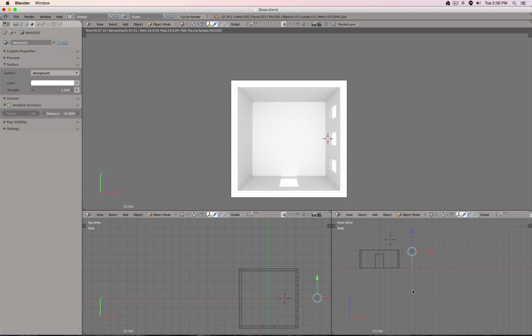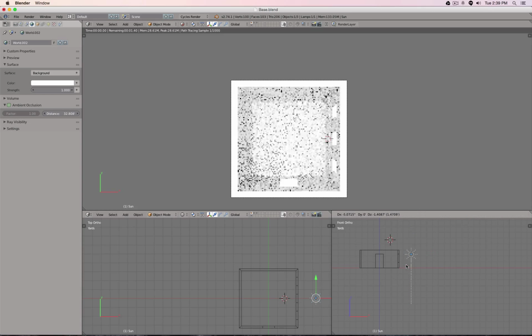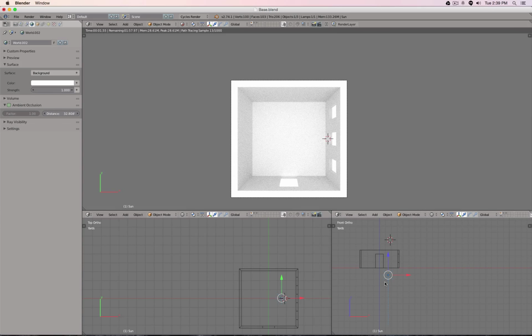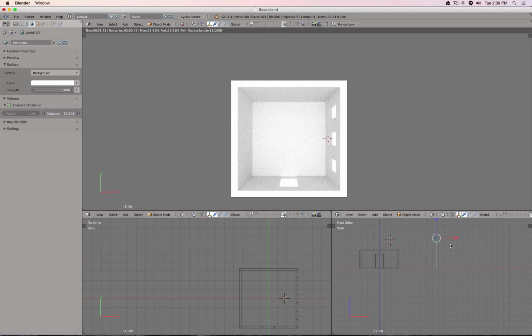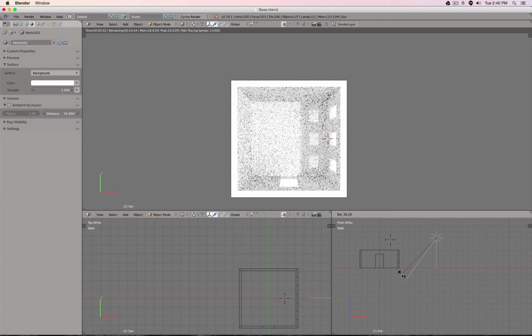That actually decides from what direction the light is being shot into or flooded into the scene. So currently the light comes from the top down. You can even put the sunlight below my house. It doesn't really matter. The sunlight is basically simulating, well, our sun. So it's directional light. That means all light rays are parallel to each other. That means shadows don't really foreshorten perspectively. But I can rotate this light and take a look at what happens inside my 3D view.